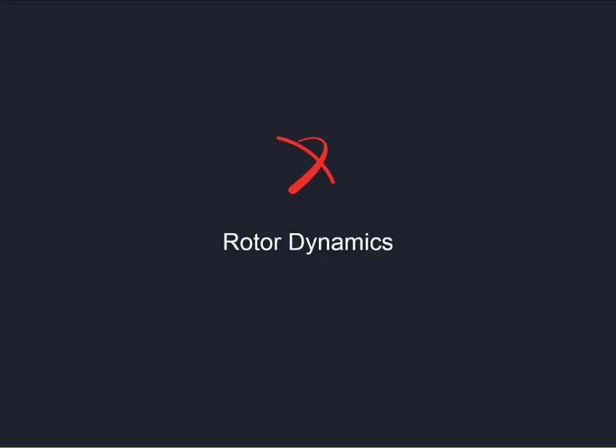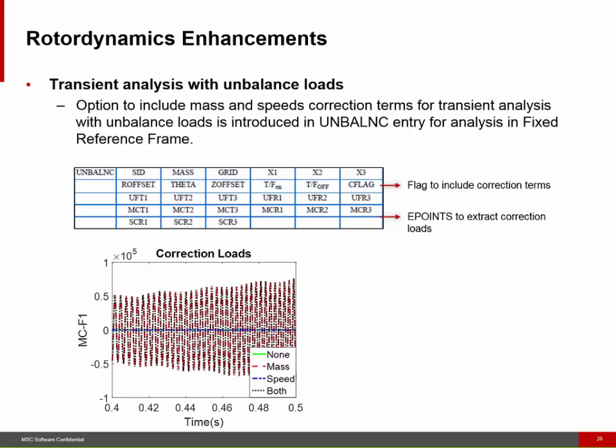Moving on to Rotor Dynamics. We've done some enhancements in Rotor Dynamics. In this case, it's a transient analysis with unbalanced load. Now it's possible to include the mass and speed correction terms to account for inertia and gyroscopic effects when you add the unbalanced mass. And those terms can have a significant effect depending on the rotor and the amount of unbalanced mass.